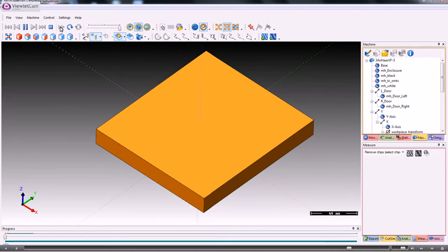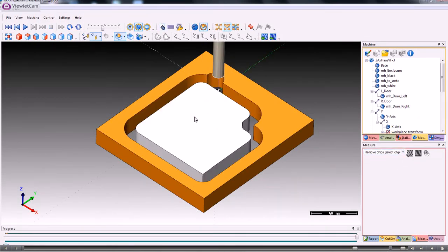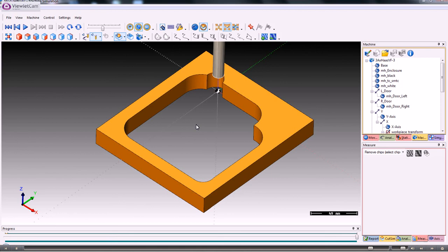and did the same thing, this time we're going to remove the chips, but if we press on the center part here, it removes the slug, so we're left with the outside. So this can be used ideally for producing the STL file that you need for 3D printing, or it can just be used as a visual aid, especially in wire EDM and milling.